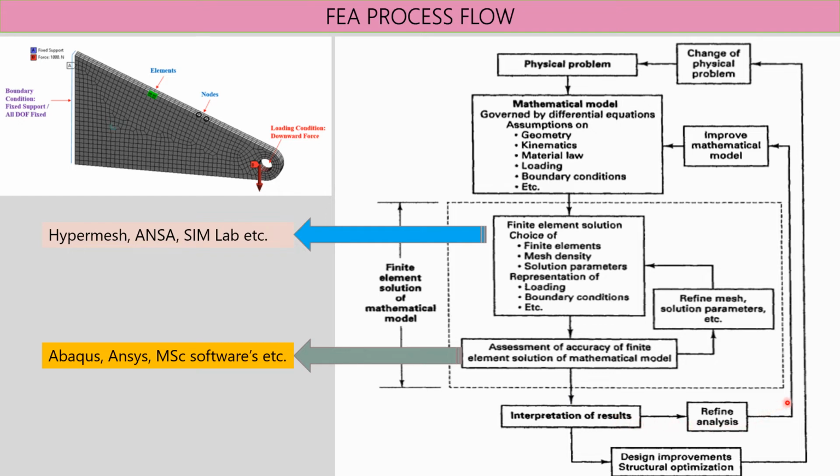If not satisfied with refining mesh and solution parameters, then we go for refining the analysis type. This refining of analysis goes back to improvement of the mathematical model.